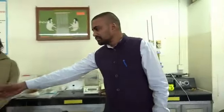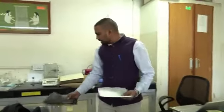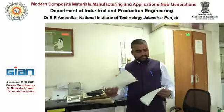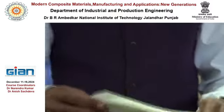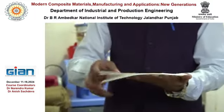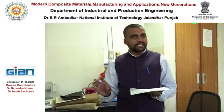So let me show you some of these fabric preforms. I have specifically prepared this for this particular session. This is the glass fabric, right? And we can produce the glass laminate, that is laminated composites. For example, we can stack the fabrics one above the other, and we can have multiple layers depending upon the required thickness.